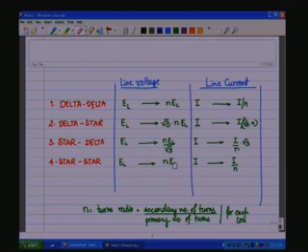In the case of the star, the windings are phase quantities. The voltage of the windings are 1 by √3 times the voltage coming across the terminals. So, the windings will have to withstand whatever quantity on the primary or the secondary divided by √3. So, it should only withstand 1 by √3 times EL and 1 by √3 times nEL in the case of